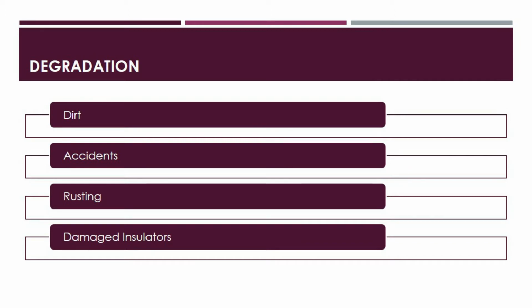A rusted switchgear enclosure can also result in perforation, posing a public safety risk. Touch-ups and repainting may postpone the rusting process, but the equipment will eventually need to be replaced. Cleaning can often eliminate grime and pollutants that have accumulated on the switchgear. Dry ice and online cleaning is a newer technology that is now in use to resolve this problem.